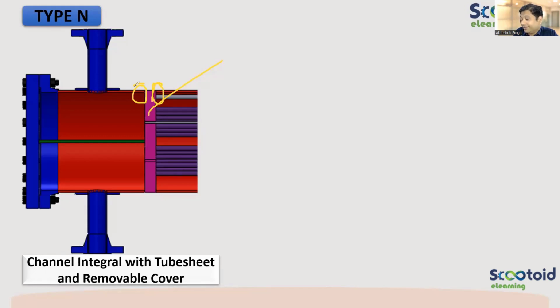Forget about maintenance, because if maintenance is required, you need to provide access. Here only the application is going to make the difference. A welded joint will be more rigid, because if you have bolted, you have gaskets, and leakage is possible. Bolted joints are always critical because there is a leakage path. If you are welding, there is no possibility of that.